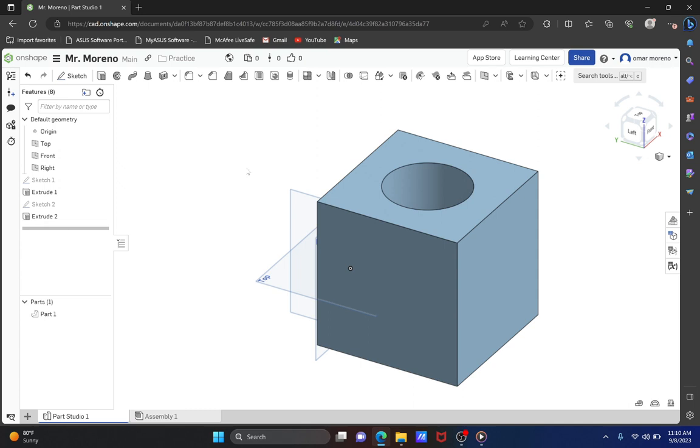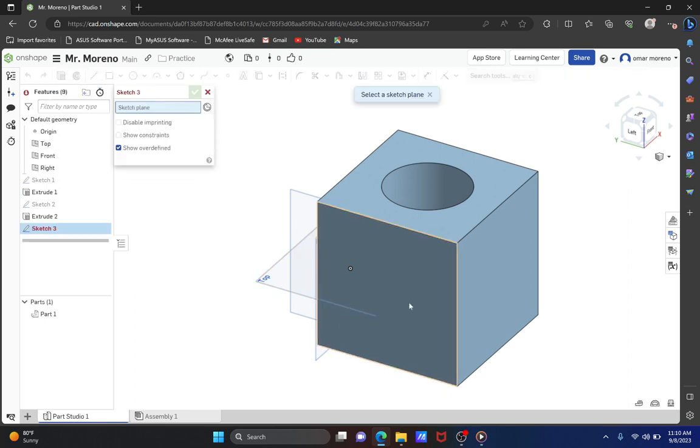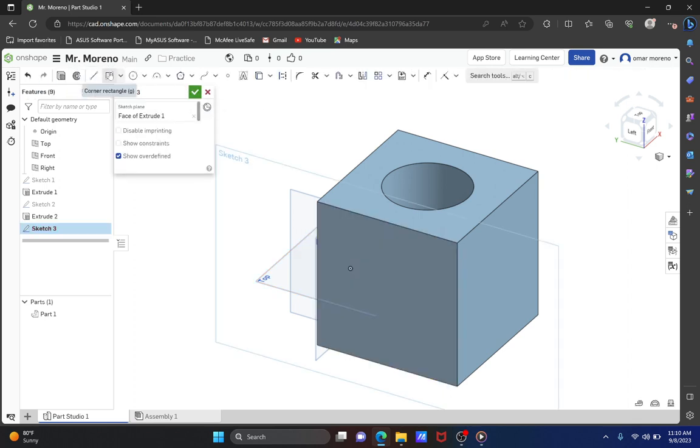Notice how everything's just based off of sketch, dimensions, and extrude, or remove. And then you go back to the same thing. You can put another sketch over here, different shape, put it in there, add the dimensions, and then you can add to it. Actually, you know what? Why don't we do that? Sketch, this face. I'll grab a rectangle in this case, and put it in there.